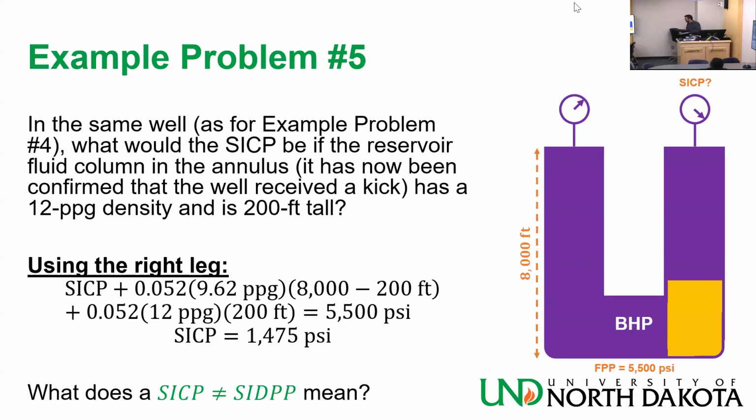And the other important thing is that it's a little bit counterintuitive that FPP and rho fluid, the density of the fluid, are completely unrelated, right? I can have a gas reservoir of very high pressure, FPP very high, and the density very low. Or the other way around is possible. I can have a heavy oil depleted reservoir, very low pressure, heavy density, right? Because once it's in my well, I care about how much the column weighs.